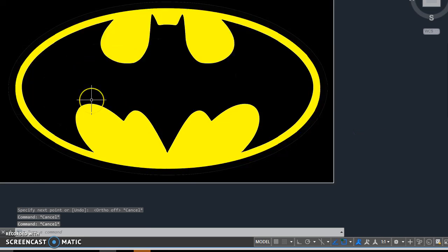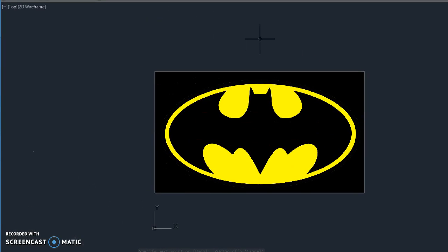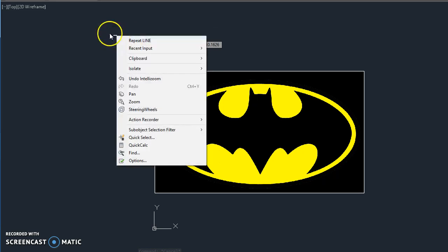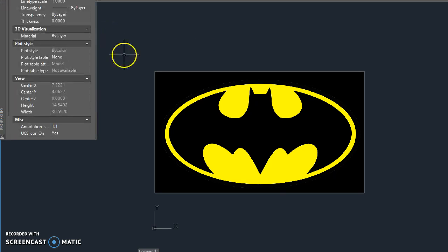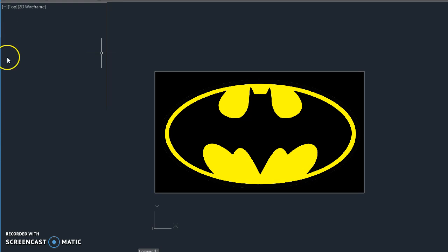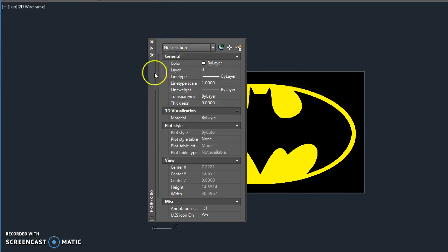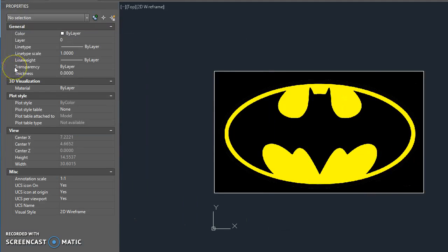Here's what you're going to do. We need to set this up for the right scale before we get going. So everyone do this, please. If you haven't already done this, press Control 1. This is a properties menu. What I just did was I grabbed it by the bar and pulled it over to the side and dumped it. You will leave this here forever. Never take it off your screen. It's a nice guideline.